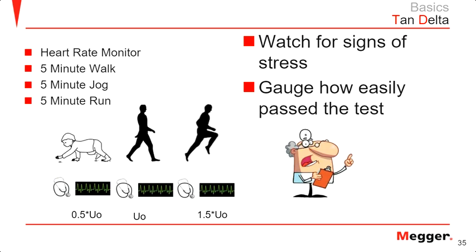But sometimes that over voltage, if it is the end of your cable, it happens there. It depends on sometimes the manufacturer who provided your kit, who did the termination on the end, and is it able to hold that voltage? And that's what all these tests are trying to determine: why does it break there? And ultimately with a partial discharge test, it can tell you what type of break was in the cable itself.